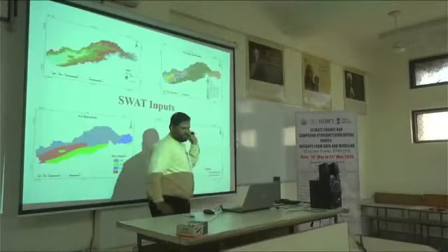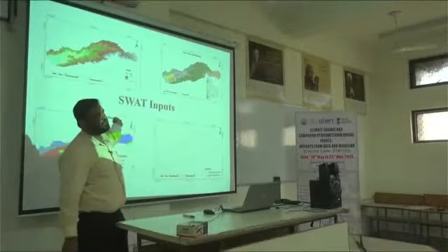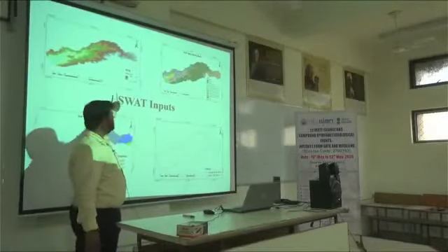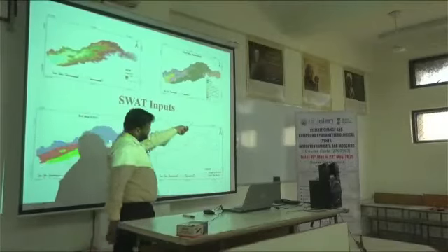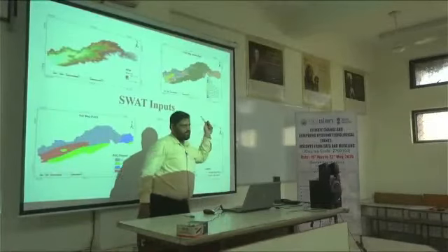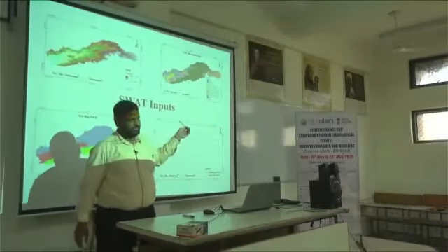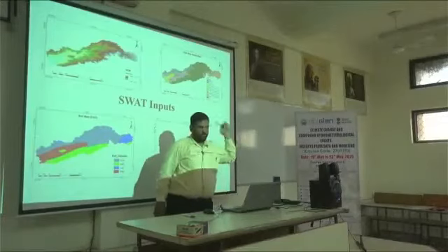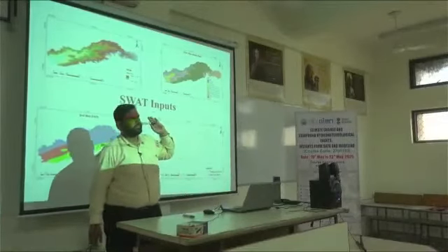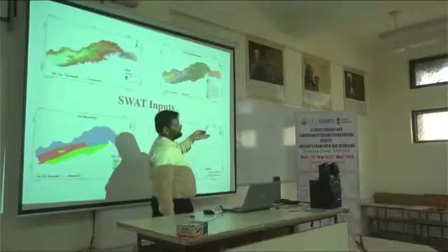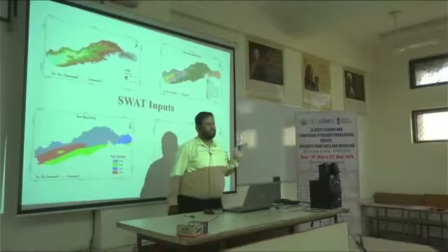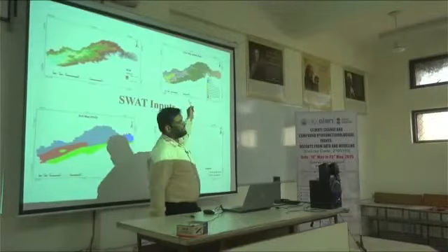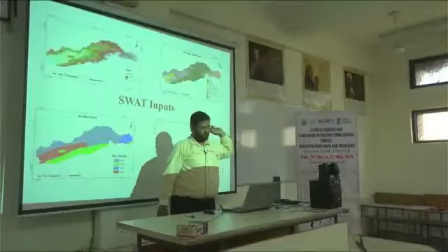These are the GIS layers which you have to create before entering the SWAT environment. We have to download digital elevation models, available from remote sensing images like SRTM, ASTER, Cartosat. Nowadays we are using ALOS PALSAR. They are available at different resolutions, 30 meter, 12.5 meters, and SRTM is also available at 90 meter resolution. I am talking about horizontal resolutions. We have to see the vertical resolutions also while doing this type of modeling.